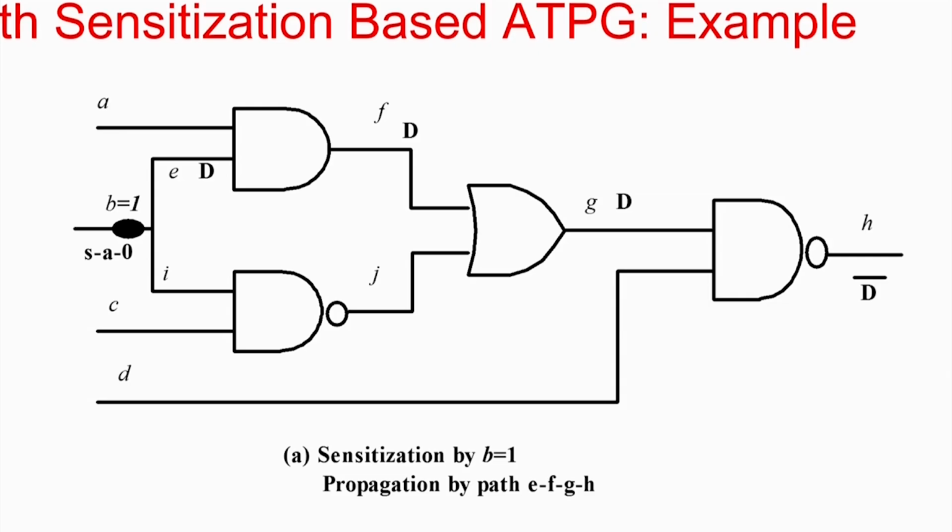That means if I apply random patterns, you could not test it. So what are you going to do? So what do you mean by sensitization? This is a very logical idea: if this line is stuck at 0, how will you test it? You have to apply a 1 over there. Obviously, if you want to test whether a bulb is fused or not, what you will do is put the light on. If the light glows, the bulb is okay, or otherwise the bulb is fused. Similar logic here: stuck at 0 means I have to apply just one pattern here.